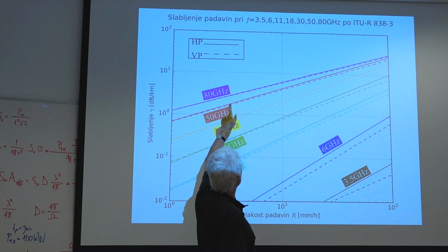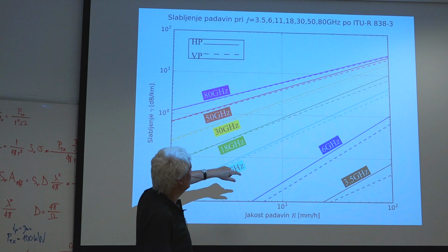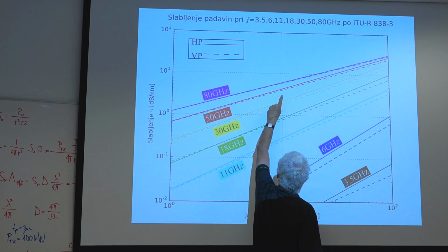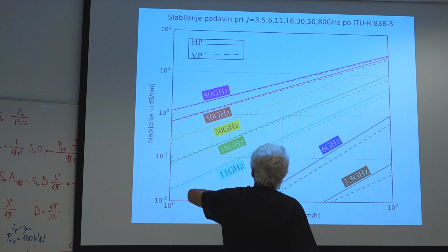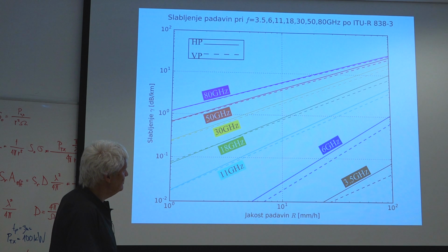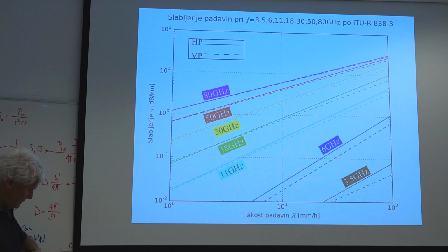Things are getting even worse when you go to higher frequencies. When you go to higher frequencies, any amount of gain you have, you kill this communication. The loss you see goes up to, say, between 2 and 5 dB per kilometer. You cannot expect this link to cover distances more than just a few kilometers in the millimeter wave range.